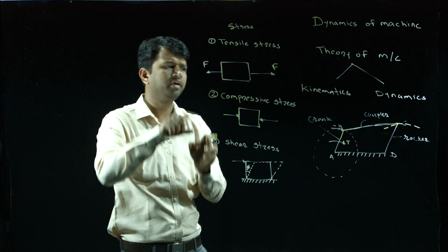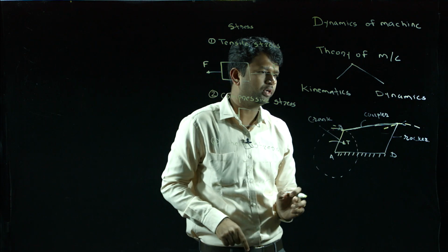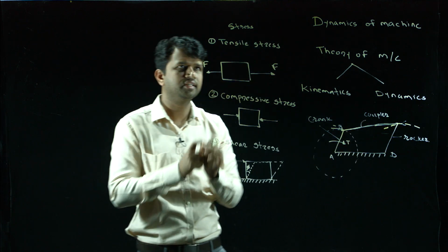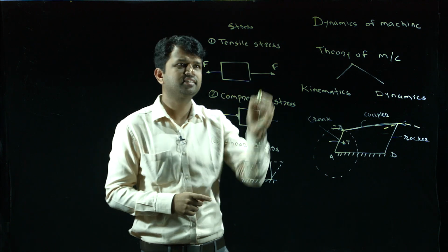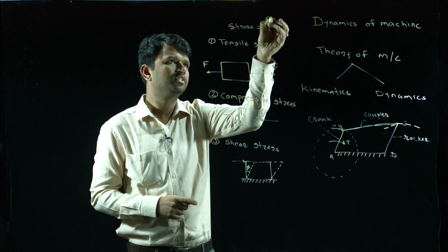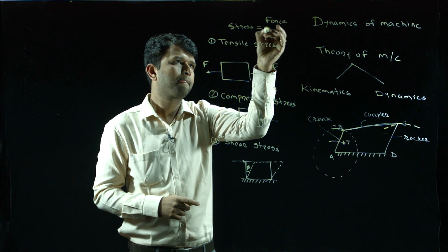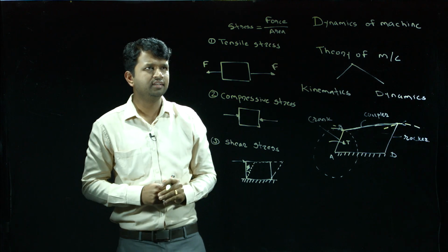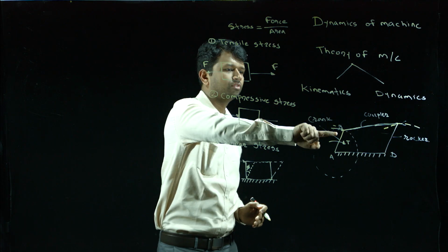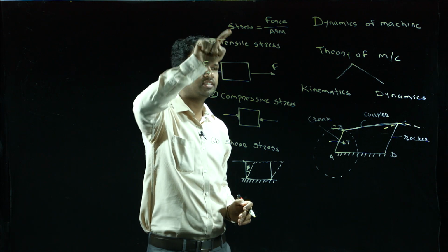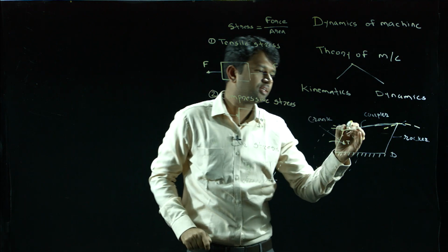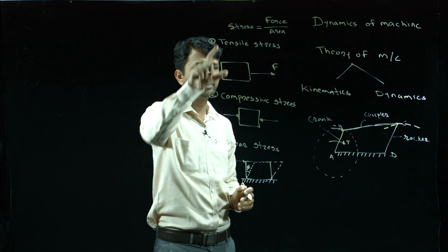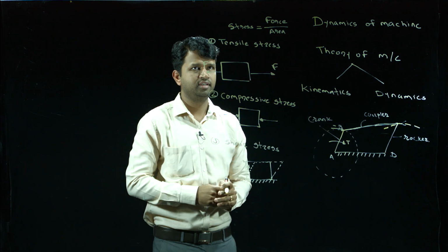Now after calculating these stresses, we can design this component. So before that, we have to calculate the force. From that force, we can calculate the stress. The formula for calculating the stress is force upon area, right? So on the basis of this force, we can calculate the stress, and this stress we will compare with the strength of this material, and on the basis of that we can design this component.